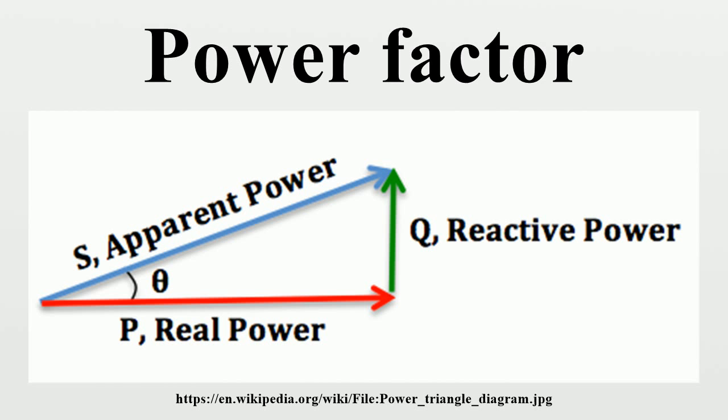Electrical loads consuming alternating current power consume both real power and reactive power. The vector sum of real and reactive power is the apparent power. A negative power factor can result from returning power to the source, such as in the case of a building fitted with solar panels when the power is not being fully utilized within the building and the surplus is fed back into the supply. Power factor correction of linear loads.